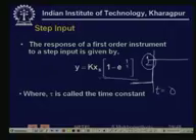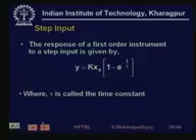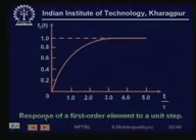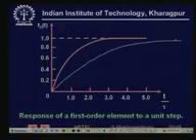Then we can compute that the time response y(t) is going to be such a function of time. The graph will show what kind of a function it is. You see that it will gradually rise and then it will become 1. If you have a large tau, it will rise slowly. If you have a small tau, it will rise fast. So this is tau decreasing.